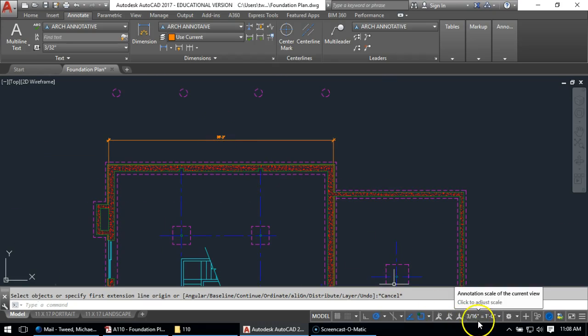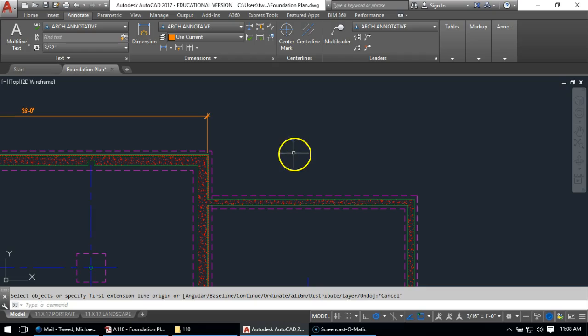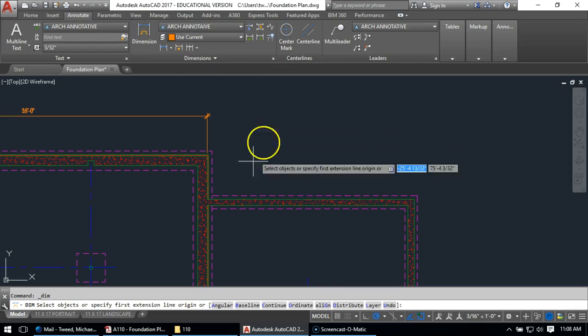If you already had it from my previous video, you want to make sure this is set to 3/16 so that the dimension comes out correctly. And wherever there's a question mark, I'm not sure why that was put there. Maybe it was just put there to make drawing a little bit more difficult, but I'm going to assume for this assignment that the question marks should be real dimensions. So I'm going to put in this next dimension, which is a question mark, and I'll just restart the dimension line.